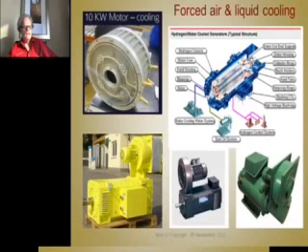Now here's a case of a big high torque density machine with an external blower on it that I don't know if that's blowing or sucking. I believe it's sucking because there's the filter system. You want to filter that air, so this sucks air in there and blows it through the machine, and it vents out both sides of the end bell, so that forces it out the end. The only thing about this, you have to keep this filter clean, so there has to be some kind of a temperature sensor or an airflow sensor that tells the controller or some maintenance people when the filters are dirty, because if those get blocked, you're going to cavitate, you won't get the proper cooling, and the motor will overheat.